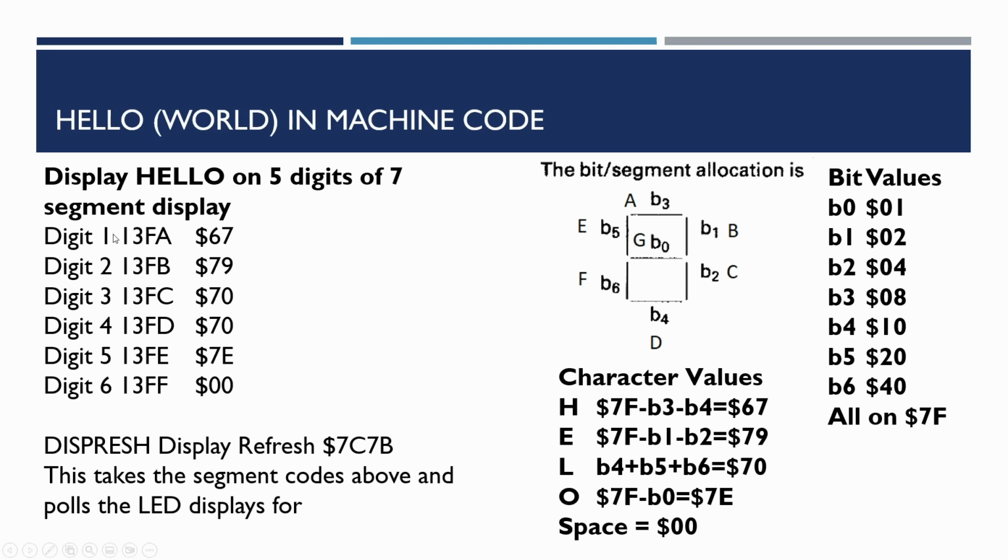But in fact, on the 6809 Nanocomp, it's actually stored in this area here. I don't believe it's actually in the Wireless World magazine article, but since I've already disassembled the monitor previously, I know where these are located. For each of the letters in "Hello", we need to work out which segments need to be illuminated. A 1 in the value will turn the segment on.